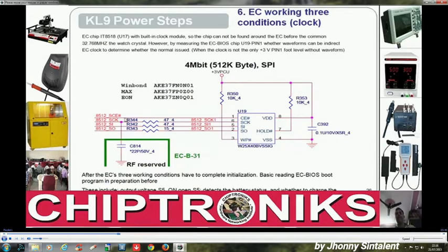If there is a waveform, that means we have to use an oscilloscope to check the waveform, right? In my oscilloscope class I'll show the various ways to check these signals, that is the clock signal of the BIOS and the IO interaction, the LPC bus, the DMI bus, we'll check the X bus, we'll check all kinds of signals.